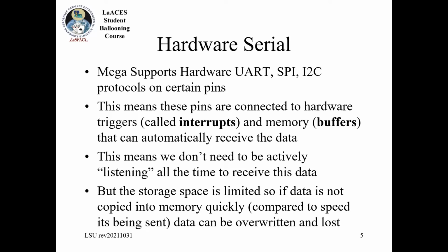But those buffers that you're sticking the data in are really not large. They're maybe 1 or 2 bytes worth. So in general, you need to copy that data out of those buffers relatively quickly, quickly meaning faster than the new data is being sent, so that it doesn't get overwritten and you don't lose it.